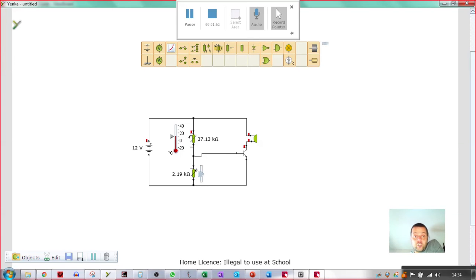So again, this could be a little plastic potentiometer that someone turns, or in industrial settings sometimes it's a screw and people put a wee screwdriver in and turn the screwdriver. You could imagine that a wee 12-volt buzzer is not going to be that loud. It's not going to be loud enough if this was on a patient in a ward that had 10 beds in it, with a charge nurse sitting at a desk outside. They might not hear that 12-volt buzzer going off.